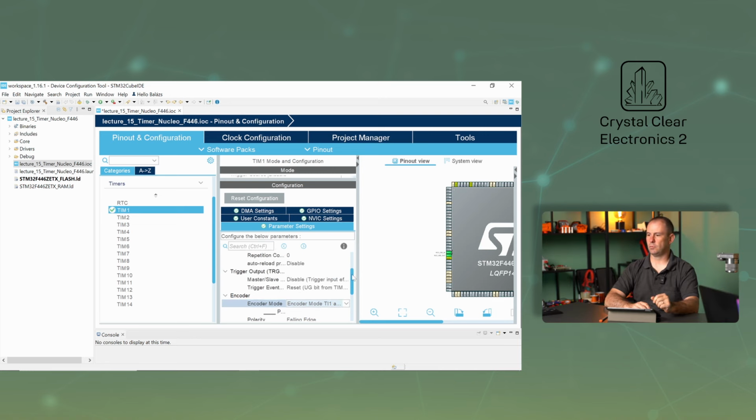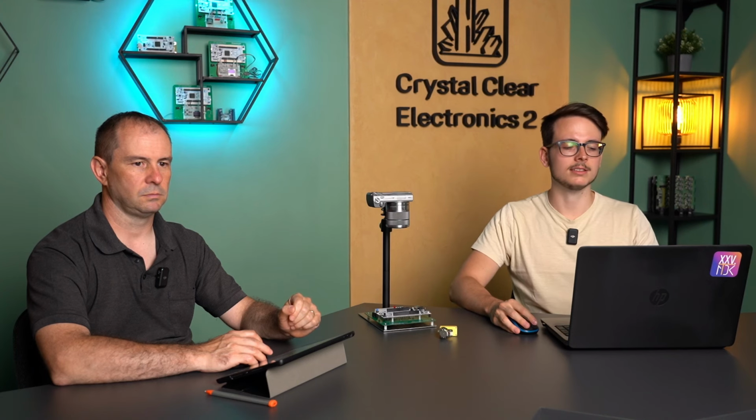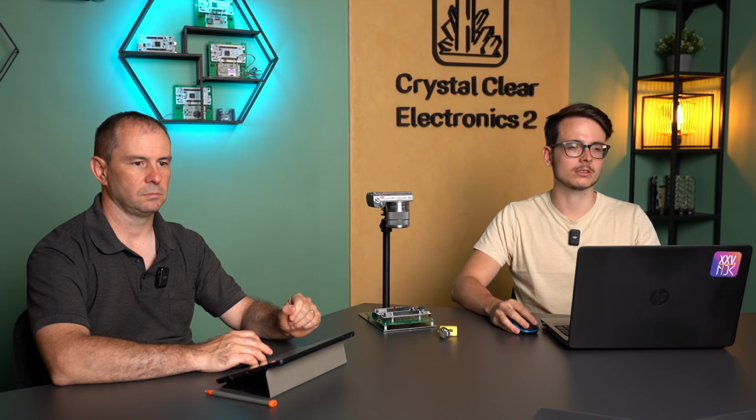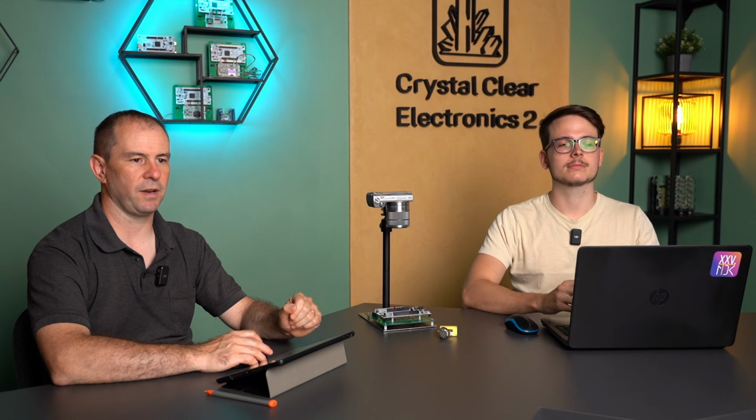Finally, we also need to set the count limit in the dedicated register. The counting register counts up or down between 0 and the limit, according to the direction of rotation. For the sake of example, let's use an encoder that gives one pulse every 1 degree of angular rotation, so we set this value to 360. There is nothing left to do but start the counter and timer module. The counter register will always contain the value corresponding to the current position.